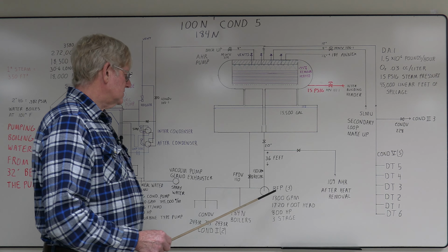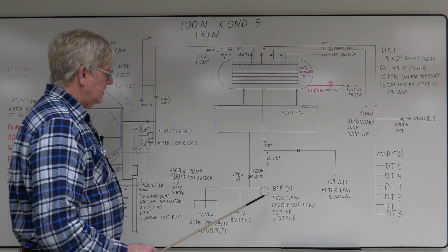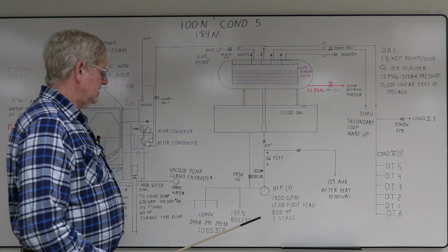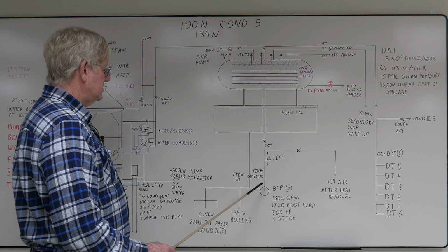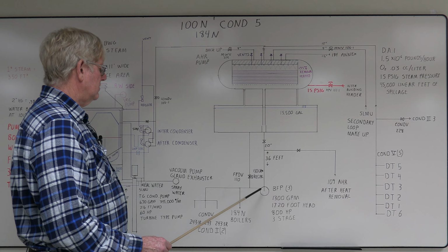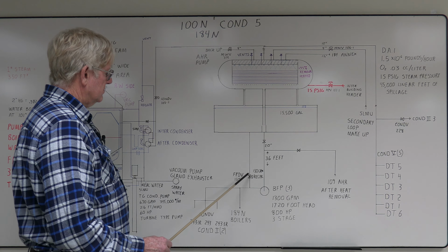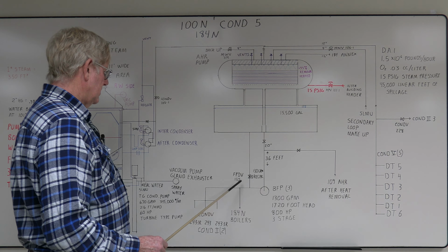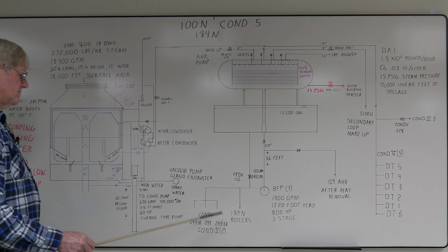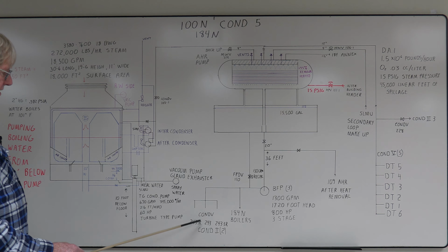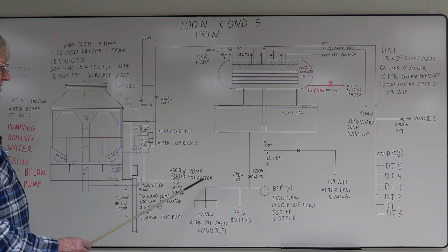Your boiler feed pumps, there's 3 of them. They're rated 1,300 gallons a minute, 1,720 foot head, 800 horsepower, 3-stage pump. They required 130 gallons a minute recirculation for pump cooling. This was an automatic valve here. From here, the water went to the 184N boilers and back to the condensate 2 header through the condensate valve, the 243s.